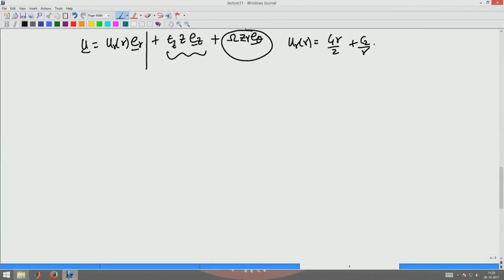Okay. In each of these cases you have to rederive from first principles, find the strain, use the constitutive law to find the stress, use the equilibrium equations to find the unknown components of the displacement field, and then you go back, plug that into the strain field and find the stress again, and that will be your solution for the problem. Okay.